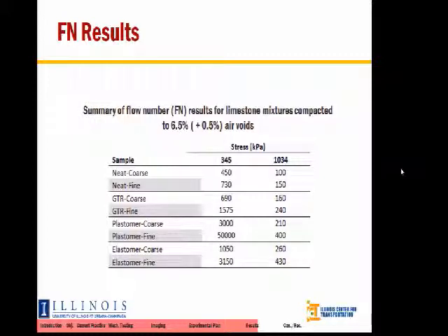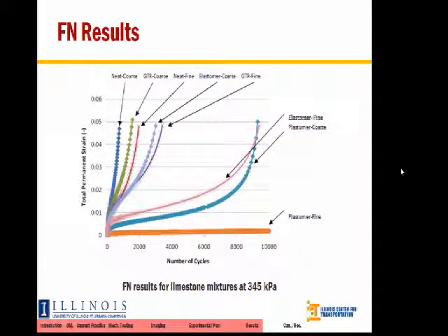Okay? This ran for 50,000 cycles, no appreciable accumulated permanent deformation in that case, which is seen by this plot. Indicative of the low stress level of the study likely being too low to be meaningful. Okay, again, 50 and 150 were chosen to span the average stress experienced in the field, 50 likely being too low in this case, because we can see the mixture that did not fail. Only plotted to 10,000 cycles here, just so I don't terribly distort everything else on this plot.